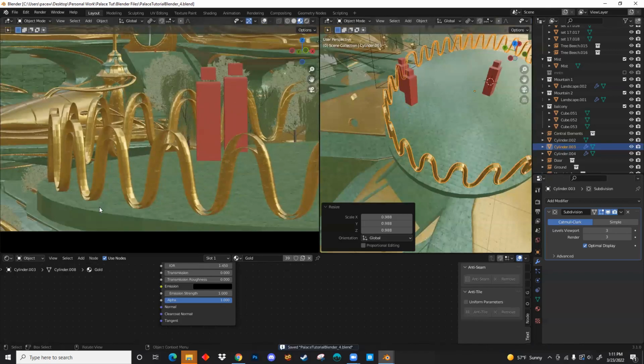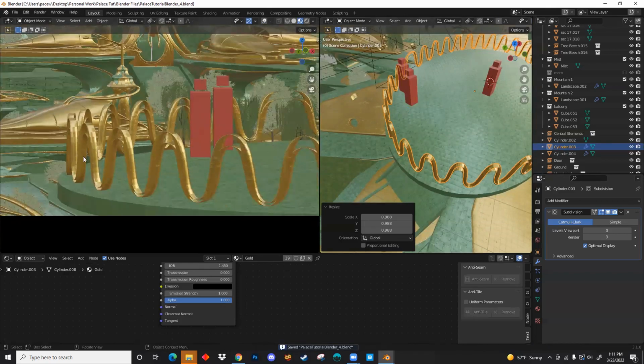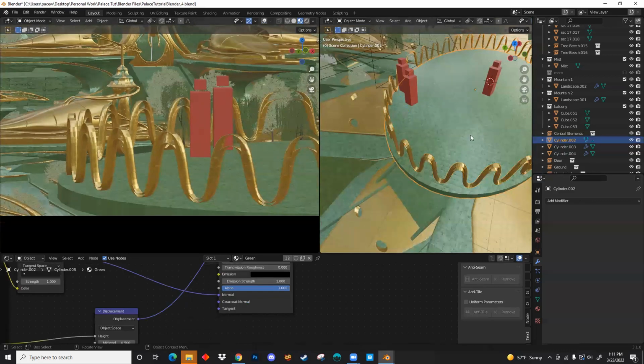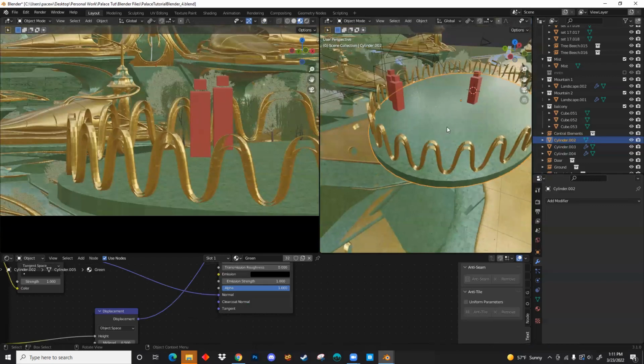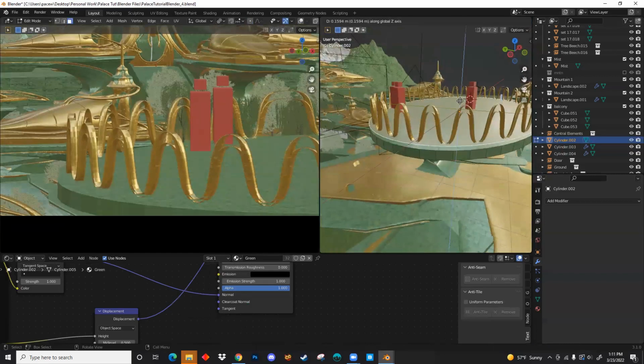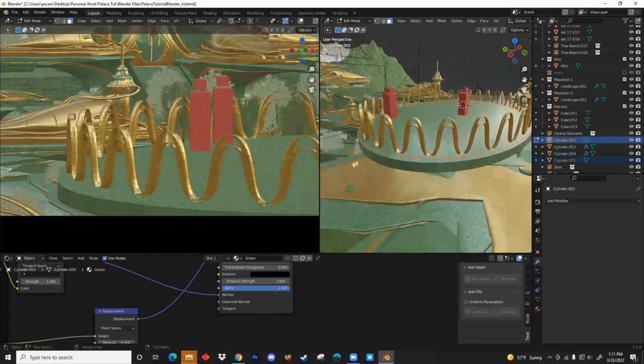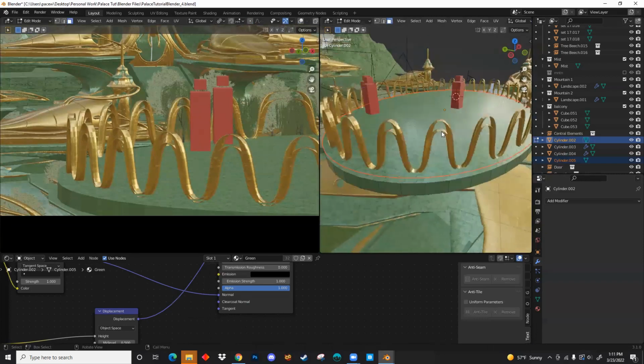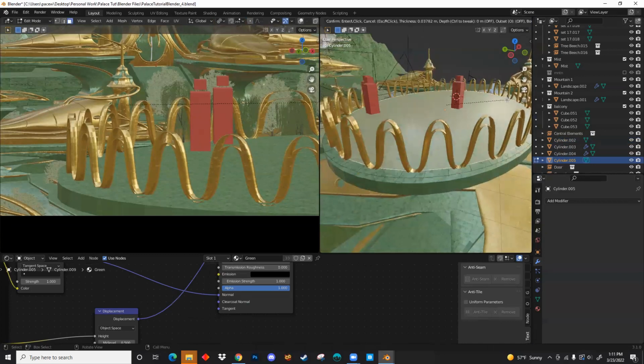All right, and then I think it might make sense for this railing to sit on its own type of material. So let's real quick go back to the cylinder, select this face, and we'll Shift D, duplicate that face up, P to separate, and now we're going to follow a similar process where we just have this face itself. I'll select that face and inset it a little bit.